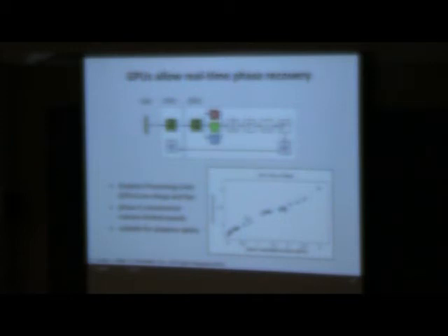So we were completely limited by our camera bringing in the data. Our GPU was computing faster than the camera could bring in the data. And we didn't have a faster camera, but we projected that the GPU would keep up with the camera until you got a camera of 2,000 frames per second. Then you would be GPU limited, and you'd have to buy a more expensive GPU. And this is space bandwidth product, so you can also include how many pixels you're doing.